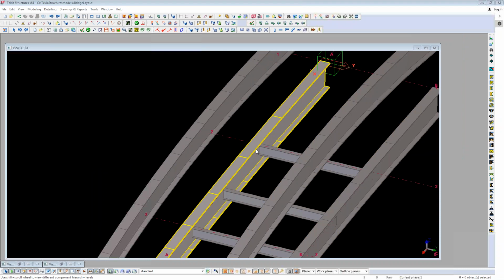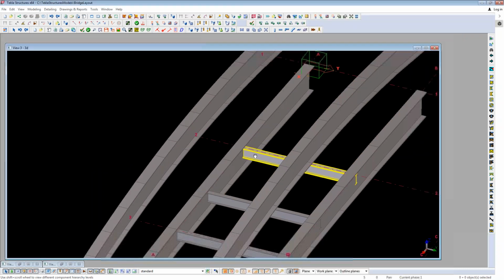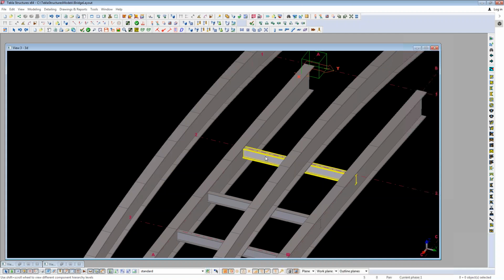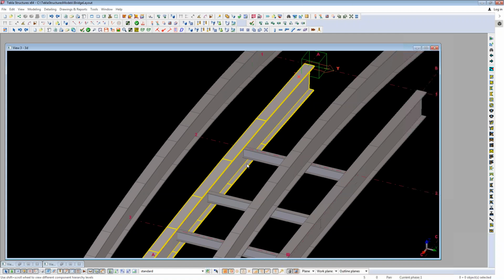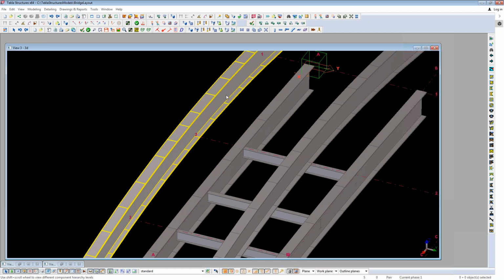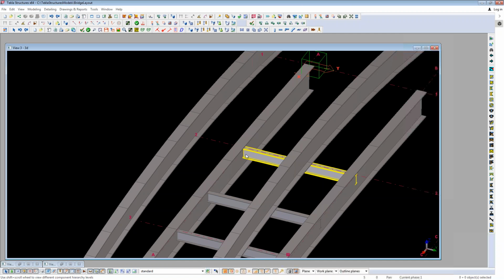There's one more powerful function. It's quite common. Let's say we have to detail the girder in the camber position, but the diaphragm has to be detailed in the final position. So we have to detail the plate and the hole in the final position for the diaphragm. Then we have to copy over the shape plate to the camber position. The connection builder is able to build one macro to do the same.